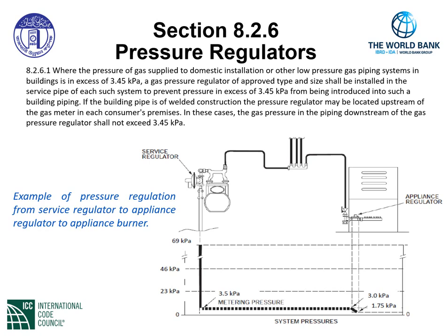The gas fitter or the people constructing the gas piping and starting the appliances will reference the manufacturer's installation instructions and set the appliance regulator to the pressure mandated by the manufacturer for proper operation of the appliance.